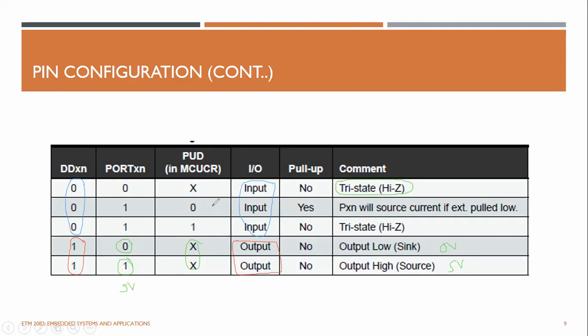And so you disable this, you write 0 to here, right? By default it is 0. When you write digital 1 to that pin, the pull-up resistors will be enabled. But if you disable the PUD, all the pull-ups are disabled from the PUD register.